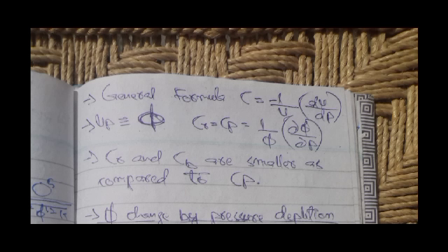It is also the basis for the definition of compressibility, which is the change in volume per unit original volume per unit change in pressure. Originally it is 1/V × dV/dP. However, the formula contains a negative sign because volume and pressure have an inverse relation between them. As we increase the pressure, volume decreases, and as we decrease the pressure, volume increases.